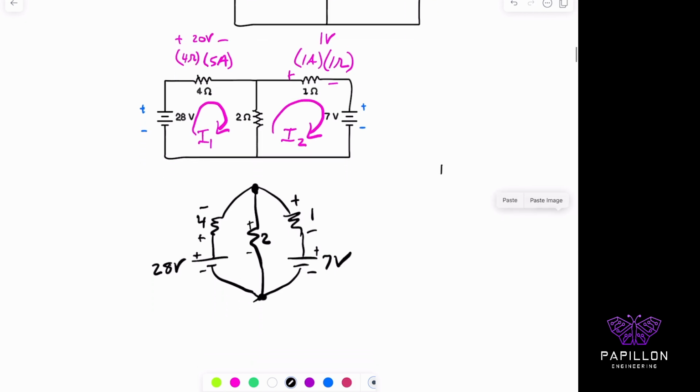So step 1, of course, is to recognize that for parallel, right, we hopefully learned that the voltages are the same in each branch. So let's see if that holds true of our understanding for our check. So remember what I said over here, that if I did 5 amps and I multiply it by 4 ohms, I get back 20 volts.